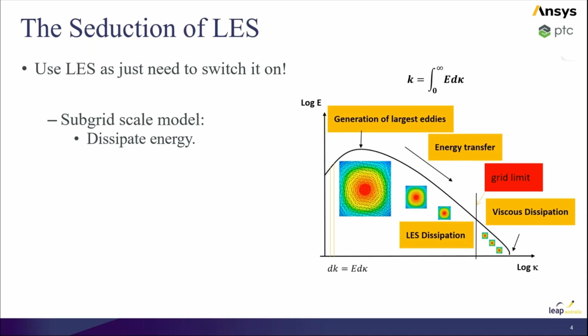And what we're modeling there is essentially viscous dissipation. And you'll see that literally the energy just dies after a certain point. And you're down there at what's called the Kolmogorov scale, where the dissipation by viscosity is so fast, we do not have smaller and smaller eddies. They literally disappear. And it's at that region that we've taken all that kinetic energy out.